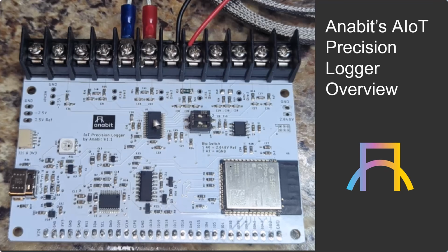Here we have an ADC from TI. This is a 32-bit high accuracy ADC. It has a mux, so it can make multiple channel measurements. It has a programmable gain amp built in. It has the 32-bit ADC, as I already said. It also has built-in precision current sources, 2 of them. So that way, if you want to measure resistances or resistance sensors like RTDs or strain gauges, you don't need any additional hardware. You can do it with just this board.